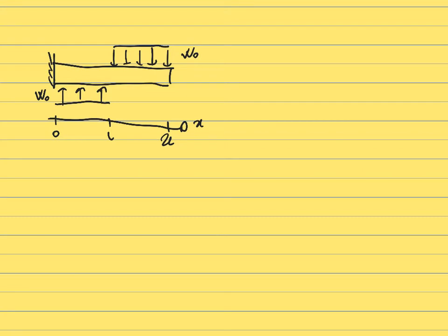So we will have a vertical force. Here in this case, it's going to turn out that this vertical force is 0. But we are going to show this in a few seconds. In this case here, we still need to define variables, and I can decide to draw this variable as going up or going down. It doesn't make any difference, but if I draw this variable in the right direction, then I will eventually find that it will have a positive value. If it turns out that I draw this variable in the wrong direction, then I would eventually find that it has a negative value at the end when I write the condition of equilibrium. So in this case, we are going to say that it's a fixed support.